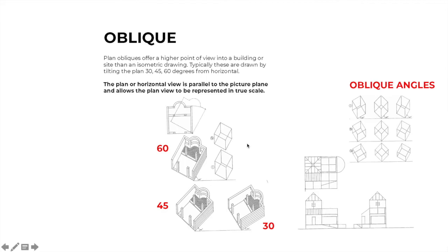So we often use plan oblique to make drawings that start to show the different spaces and complexities and features of a space. We may have pulled off the roof in this case, but you can see Ching here has taken a plan view, rotated it 30 degrees using a 30, 60, 90 degree triangle, started to project up these columns and walls, and we can start to see a better picture of what is the intention for the space.